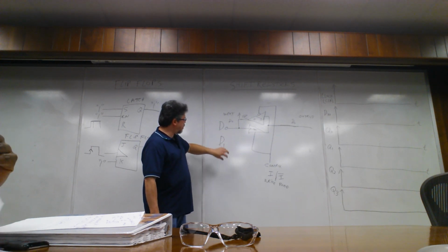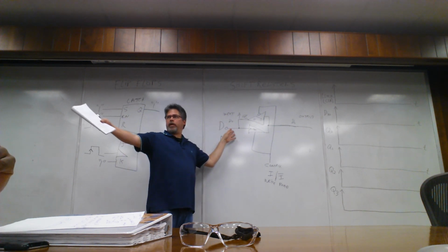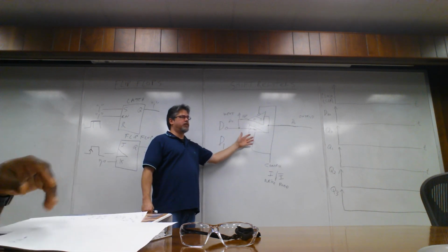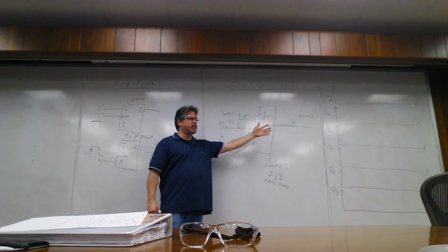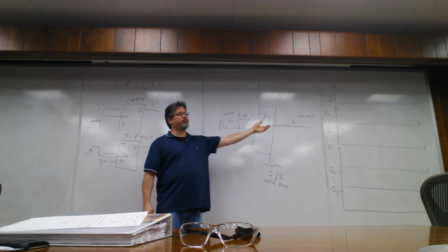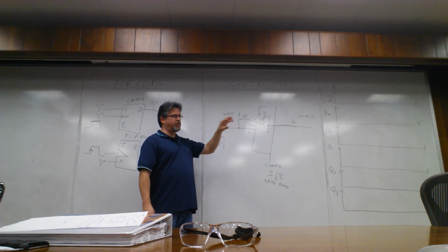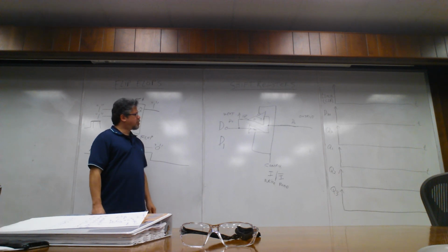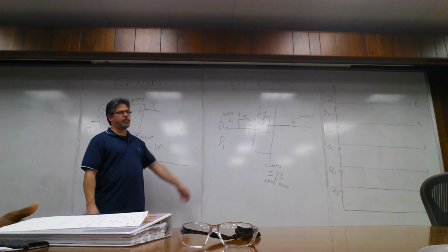So it's D0, D1, D2, every bus has it. The other thing is, like in the microprocessor system that I have here, they share the bus with the address and data lines, which we'll talk about later too. In one direction the micro's addressing a particular device, and the other direction it's actually reading data back from the device. So it's actually sharing the same lines. They call them address/data lines. It's a way of simplifying the routing of printed wire traces. Otherwise you'd have a billion traces on it.